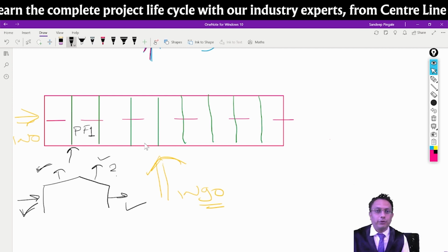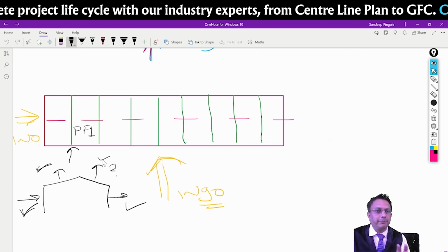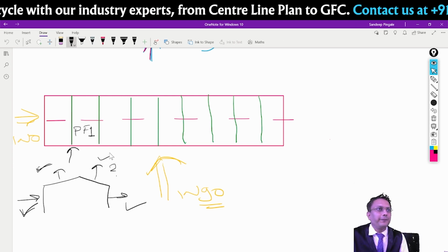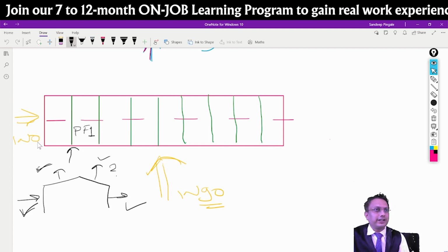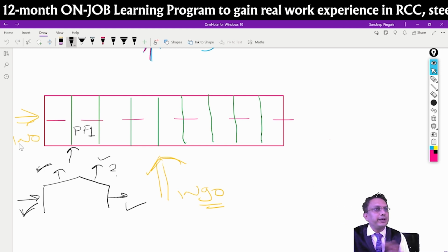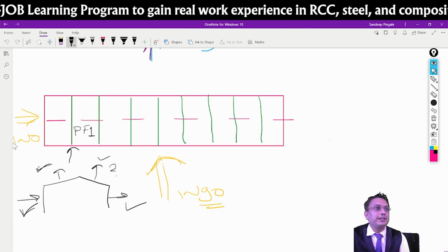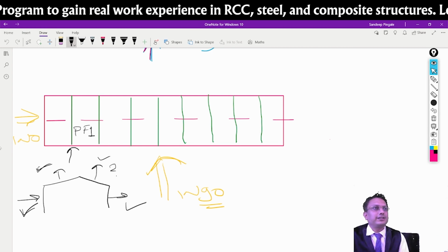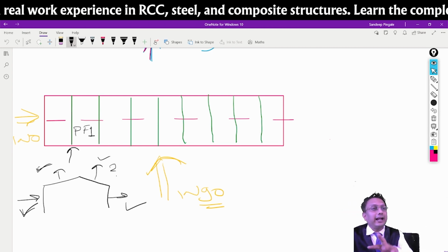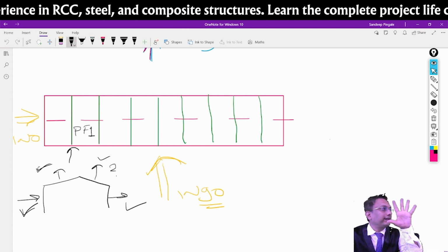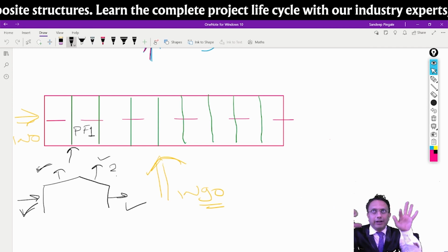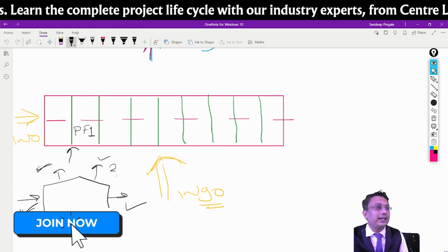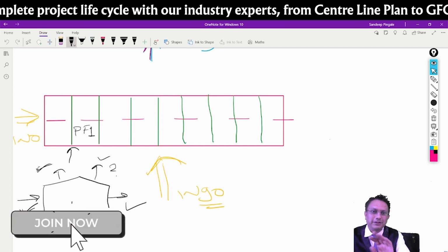Now, if you want me to recall the calculations, you will have Pz equal to 0.6 Vz square. Vz is what? Vb into K1, K2, K3, K4. Vb is what? 33 meters per second, whatever value you are getting. Then the coefficient Cp equal to Cpe minus Cpi, external pressure coefficient minus internal pressure coefficient. Depending upon that, and that figure you will take twice. One is pressure, another one is suction. Is it clear? So that data is getting scrutinized with a variety of different parameters. Tomorrow you are going to do the Excel sheet and show it to me. A small Excel sheet, like the one which I have shown you.